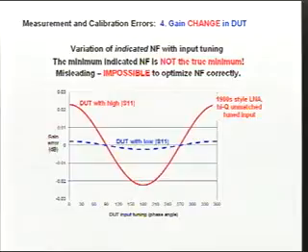So that's the difference. The 1980s style of LNA, which was what prompted Reiner to do this work in the first place, versus a more modern one with better input matching. And what's happened in the meantime since the 1980s is noise figures in general, we believe, have come down, and this error then becomes quite important. So it needs something with good input matching to push that error down below the threshold of concern again.